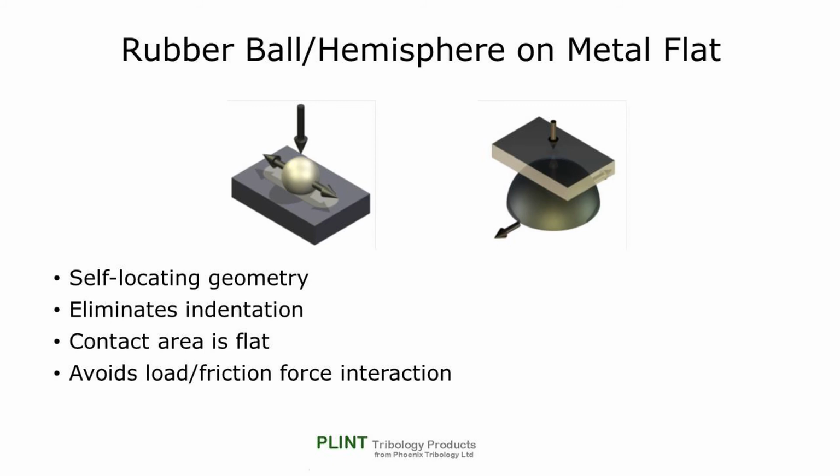Depending on the rubber under test, unidirectional sliding can result in high wear rates and pattern abrasion, with macroscale ridges forming in the surface. Testing the same material in reciprocating sliding may suppress the formation of pattern abrasion and generate lower wear rates, with a much finer scale surface roughness produced. This is intrinsic abrasion as defined by Schallamach.